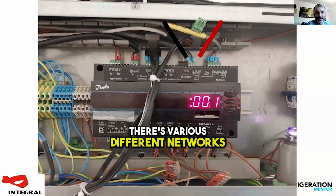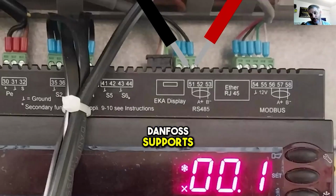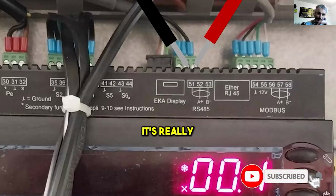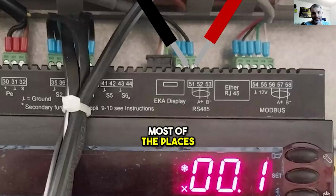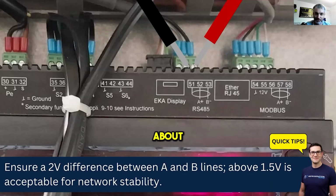There's various different networks that Danfoss supports. In the UK, it's really common to use the Ethernet connection. Most other places, they like to use the RS485 with the Danfoss front ends. So you should have around about 2 volts difference between your A and your B line. The 485 standard is anything above 1.5 volt difference so that it can see what's going on.